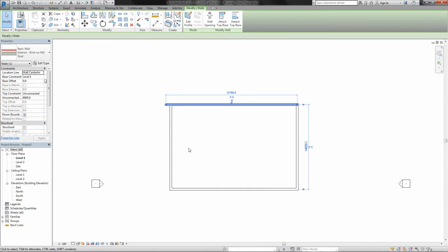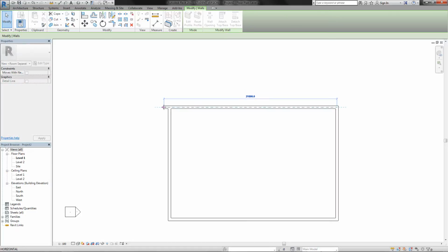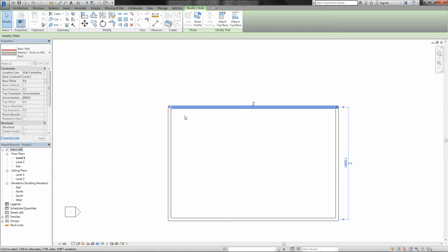As soon as you have one object selected here, you'll see a bunch of different information showing for you. So you have points at the end of each object where you can move or you can change sizes of it. You will also have dimensions where you can see the actual dimensions, and you have where this dimension is defined from. So talking about the dimensions, you have this guy where you click and it will say end, start, or center point will define my dimension.